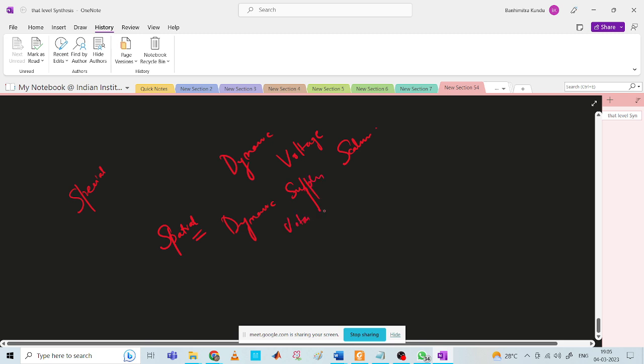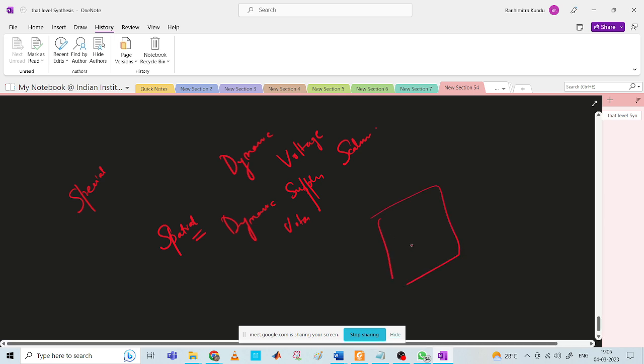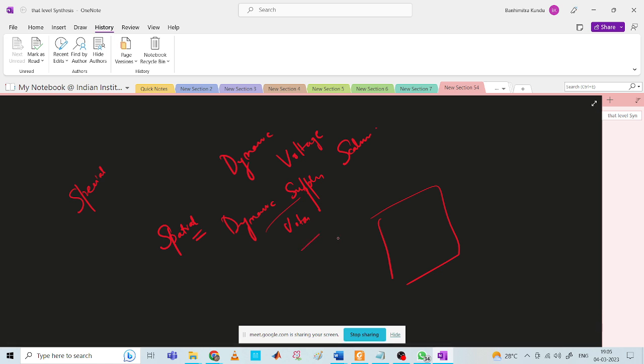Okay. See what happens in this is in terms of all the ASICs that you make. So you're finally making one chip. So dynamic voltage management or scaling, what it means is, let's say that one unit, sometimes, let's say you are powering this with 3 volts, and let's say this is working.